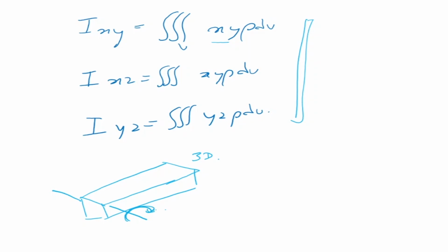It will have a particular energy requirement or amount of torque required to rotate it. And that will depend on the mass distribution of the body. What characterizes it is the inertia tensor I, which has these 9 elements. So the first thing that we need to do in our study of dynamics is to find out the mass distribution of the links.